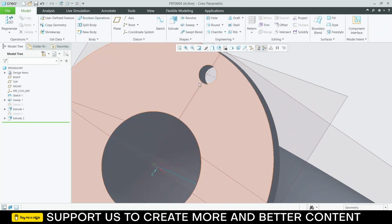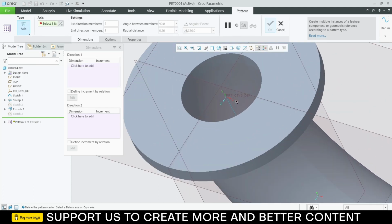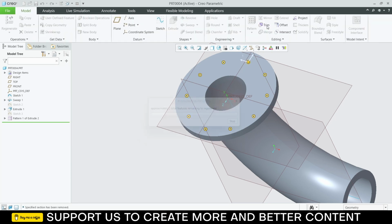So what I can do is select this extrude. Click on pattern. Instead of dimension, I will choose axis. And here I will choose this. Click on angular extent and just increase this number. Let's say 10. Click OK.